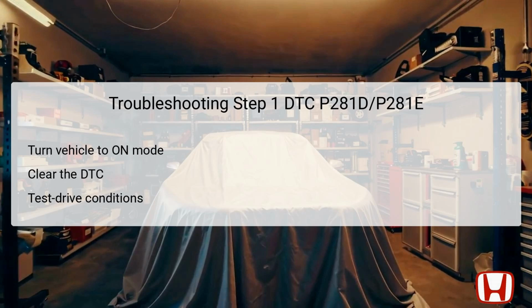After clearing, the next critical part of this step is to conduct a test drive under specific conditions. These conditions involve starting the engine, shifting the transmission to D position, while pressing the brake pedal for at least 30 seconds. For P281E, the test drive process includes additional steps, such as shifting to P and turning the vehicle off before starting it again. This series of tests will help confirm if the fault reappears, aiding in isolating the problems related to these DTCs.